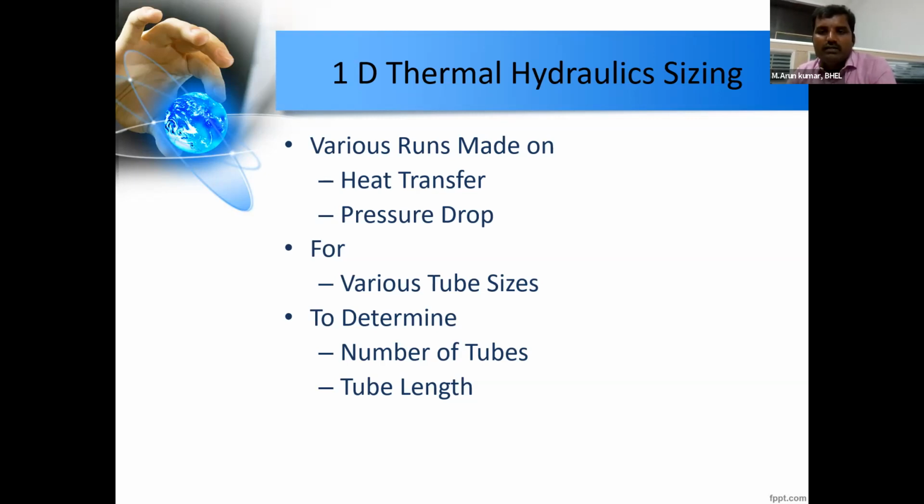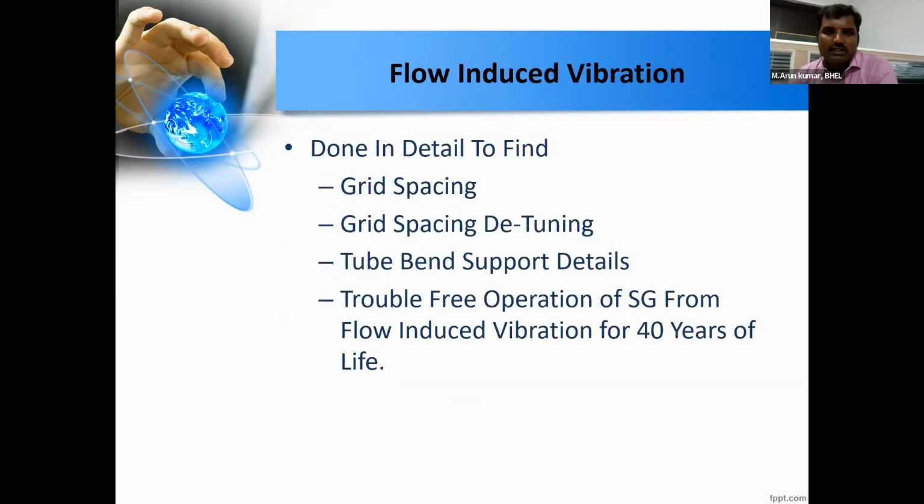At that time, we did not consider this 3% boiling. There is a scope of 3% boiling that also gives some amount of heat transfer. So we considered that in the case of 700 megawatt, based on which we could extract from the same number of U-tubes, of the same size, 700 megawatt, that is 200 megawatt electric extra power from the same design.